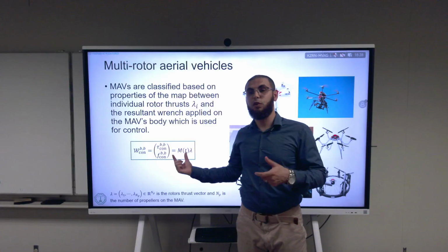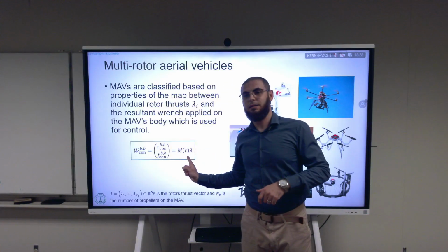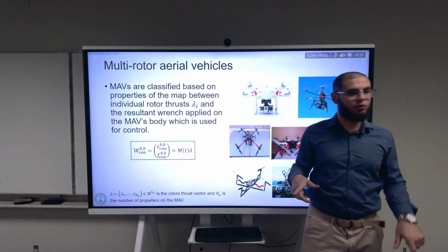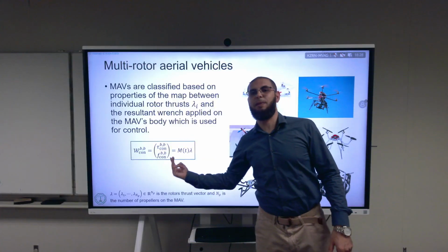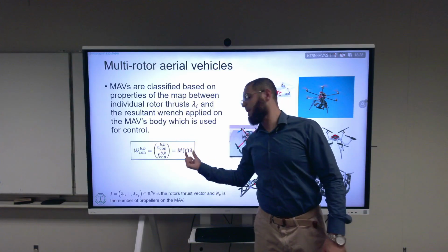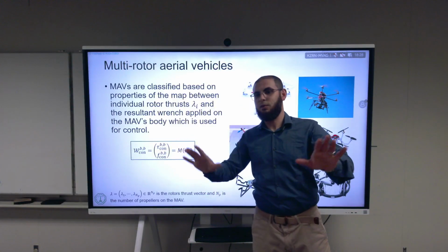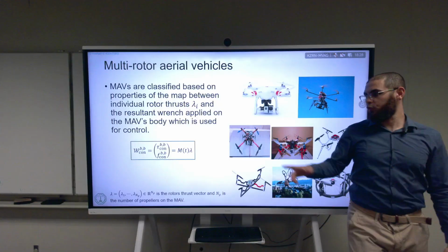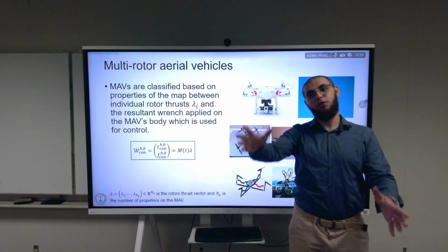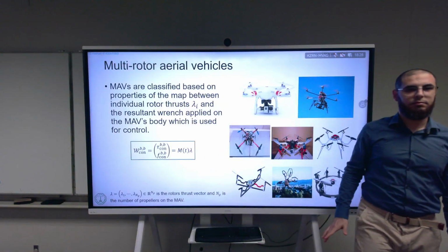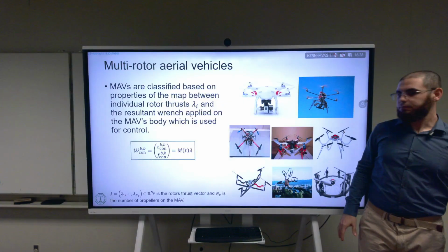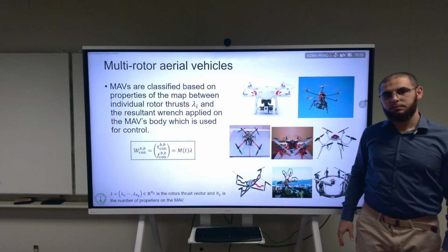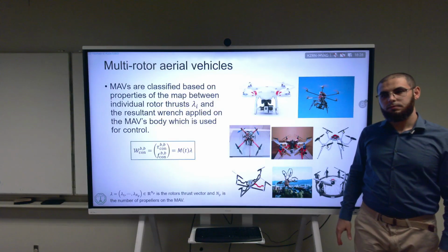Afterwards, taking this and converting to that becomes just a control allocation problem. For those who have the fully actuated drone, this is simply inverting a 6x6 matrix. That's not dependent on time, so it's an invertible matrix. That's the main reason why I told you to choose the fully actuated hexarotor, because the control allocation problem is very easy. If not, it becomes a problem by itself. But that's invariant to the default orientation of the URDF, of the base link, for example.